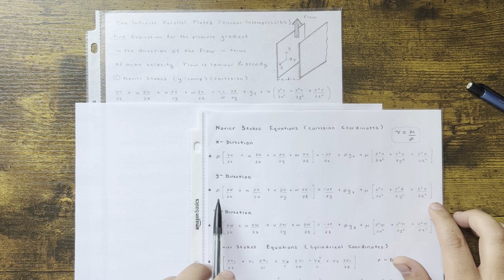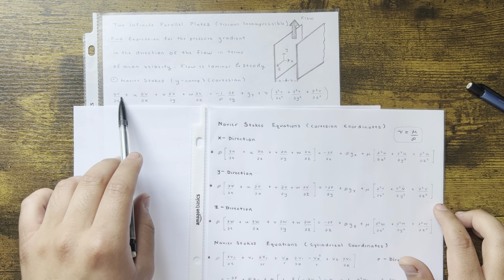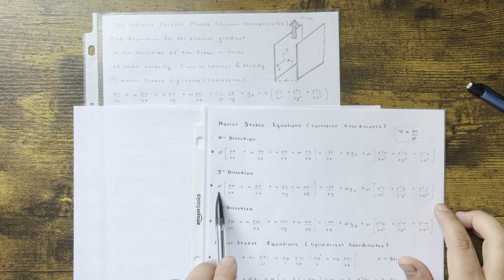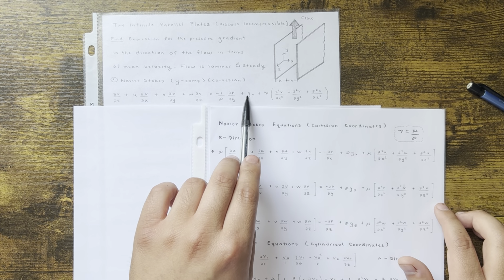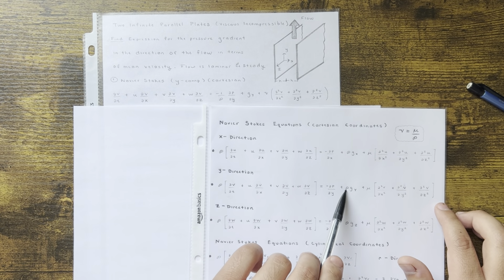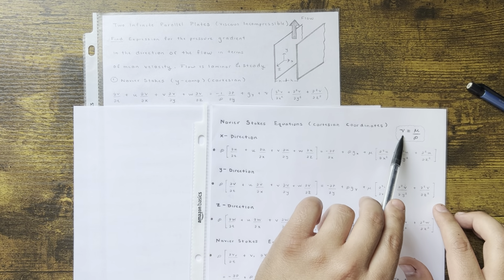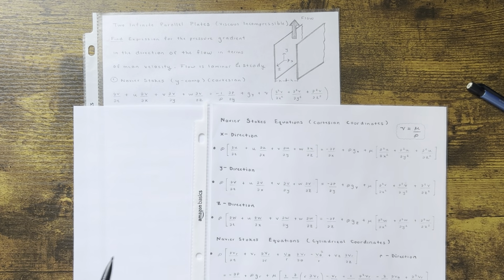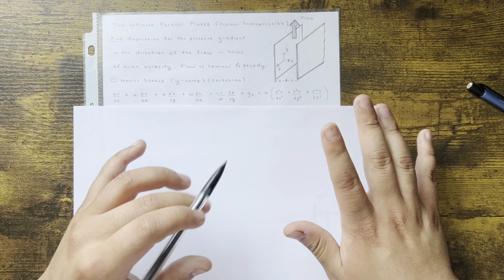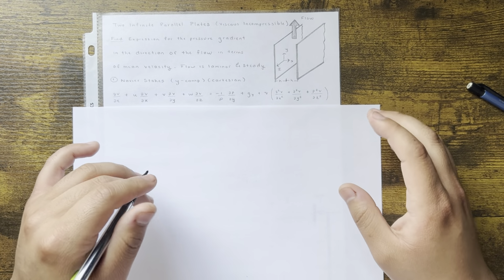So this is the one that you see in the book, but what I like to do is divide everything by density. All this stays how it is, up to here. You have a -1 over density, because this is negative as it is. You have just g_y, because that density went away. You divide by density on both sides. And then mu over density, that's just nu, so I just replace it there, and that's it. No big deal. So we start off with the equation, and it looks scary, but you just start simplifying from here. It's pretty straightforward. You'll see that this crazy equation just reduces to very workable terms.